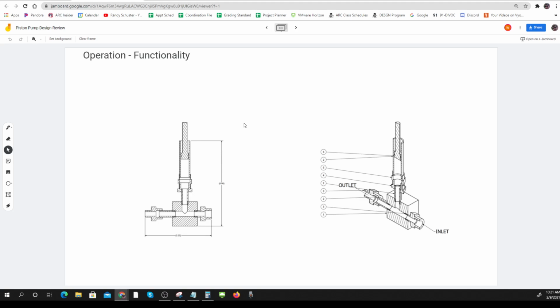What is the capacity? So somebody's going to say, okay, if it's a half inch, then we're going to be able to pump blah, blah, blah. And somebody will go, well, yeah, but if my tube is 40 feet long and it's a 3/8 inch diameter tube, that's going to take a while to clear the water out when I do this. And you're going to need to be able to do those calculations right then and there so that you can give that information.